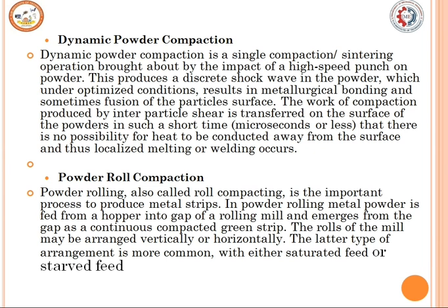the particle surface. The work of compaction produced by the inter-particle shear is transferred to the surface of the powder in such a short time that there is no possibility of heat being conducted away from the surface, and thus localized melting or welding occurs.